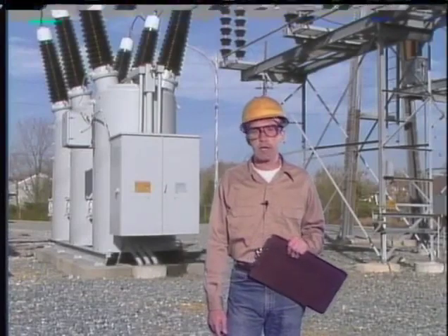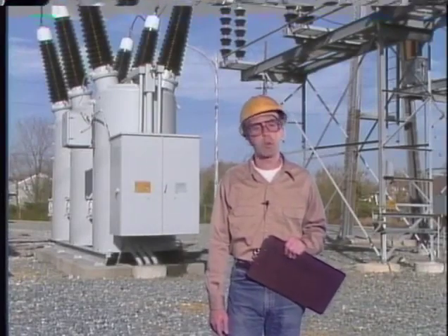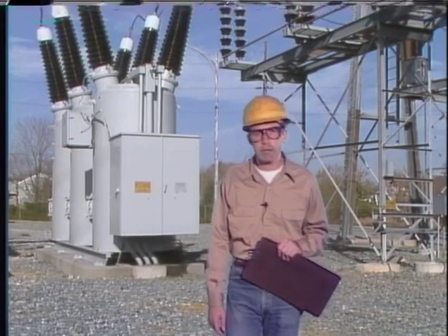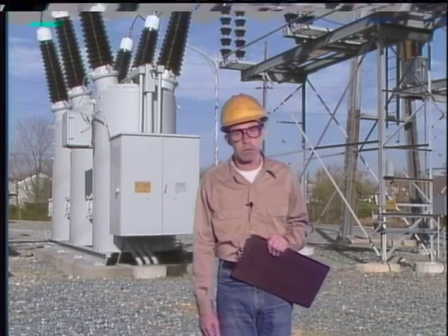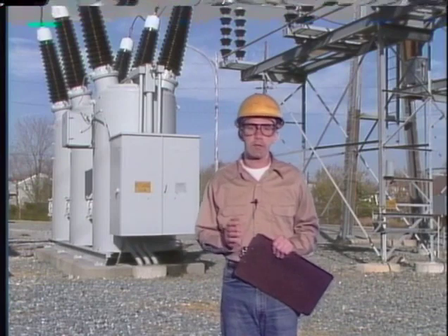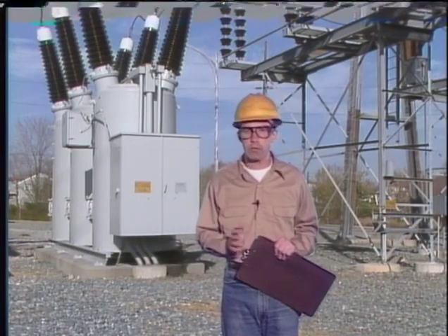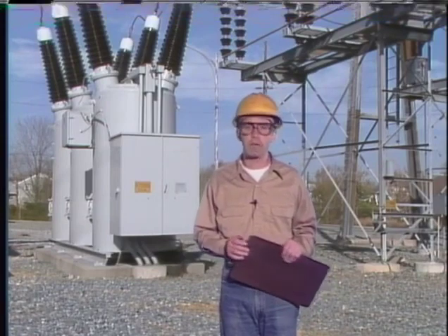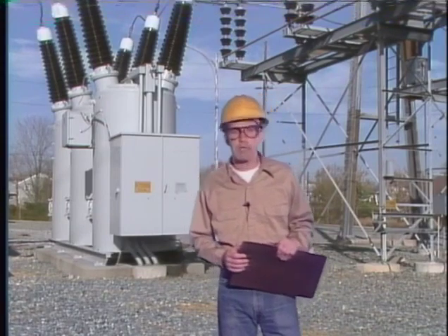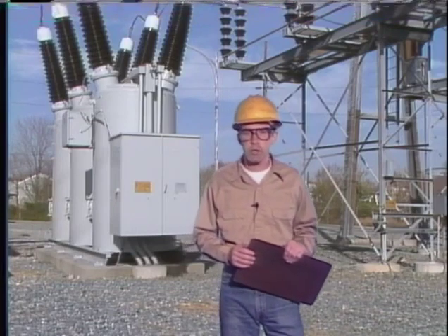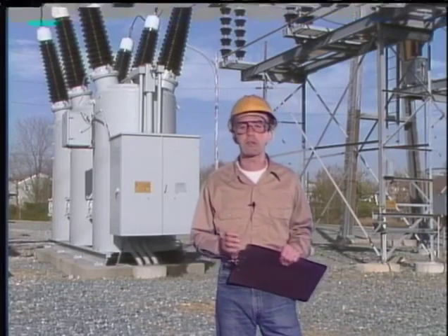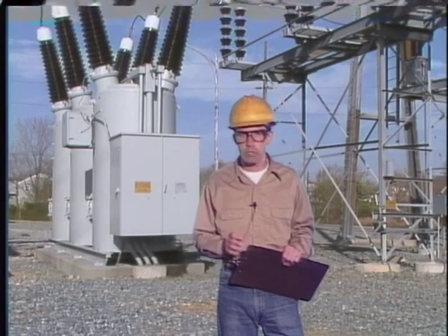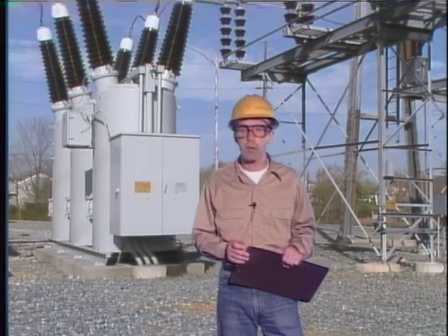Some of the maintenance tasks that apply specifically to oil circuit breakers involve handling or checking the condition of the oil. These can include checking the dielectric strength of the oil, removing and filtering the oil, ventilating gas byproducts of the oil, and rinsing dirty oil off the breaker mechanisms. Other tasks that are specific to oil circuit breakers deal with inspecting components that are unique to OCBs, such as the interrupter grids.